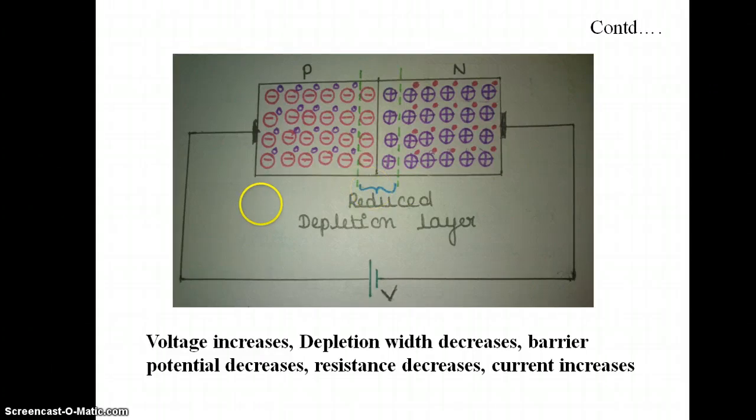For each combination of a free electron and a hole, an electron from the negative terminal of the voltage source enters the N region and then moves towards the junction. Similarly, the P region is nearer to the positive terminal of the voltage source, so an electron breaks a covalent bond in the crystal and enters the positive terminal of the voltage source.